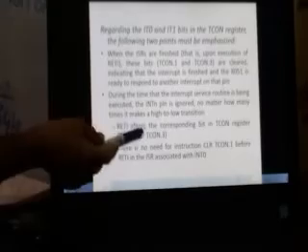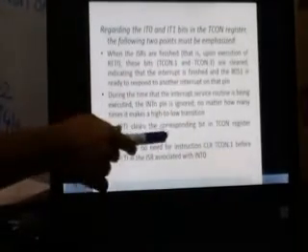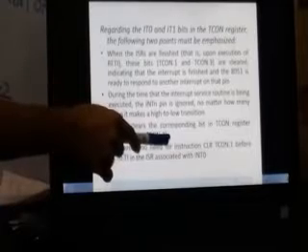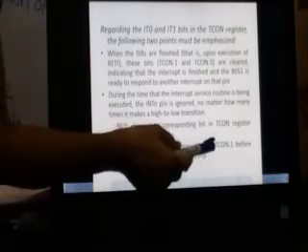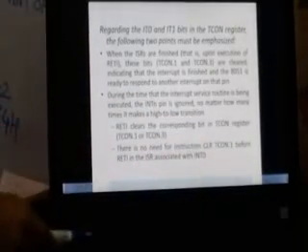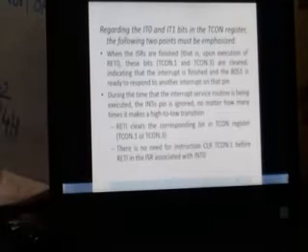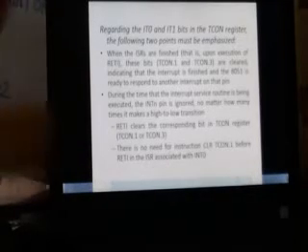RETI clears the corresponding bit in the TCON register, that is IE1 and IE0. There is no need for instructions like CLR TCON.1 and CLR TCON.3. We need not do it. That's not required. So this much you should know about external interrupts when they are edge triggered.